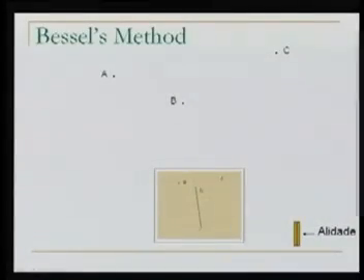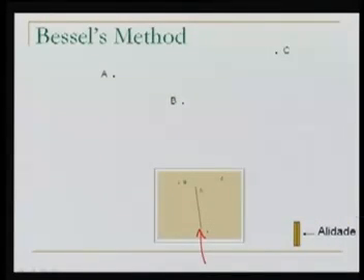Well, the resector is drawn here. That's the resector. Second, I keep the alidade at small c. I can do it for A also. At small c, rotate the alidade now. The table is not being rotated because the table is oriented and clamped. I only rotate the alidade so that capital C there on the ground is bisected. I draw a resector. Let's do it. Now here, I'm sighting C, drawing a resector. So we get a point of intersection here. Obviously, as we understand, this point of intersection is the point where we are, which we say is small p.